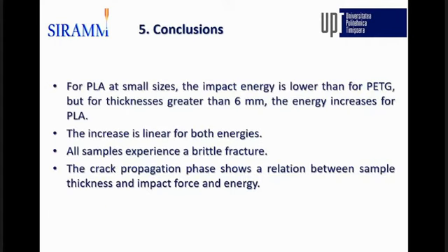Conclusion: for PLA at small sizes, the impact energy is lower than for PETG, but for thickness greater than 6 millimeter the energy increases for PLA. The increase is linear for both materials. All sample experiments show brittle fracture. The crack propagation shows a relation between sample thickness and impact force and energy.